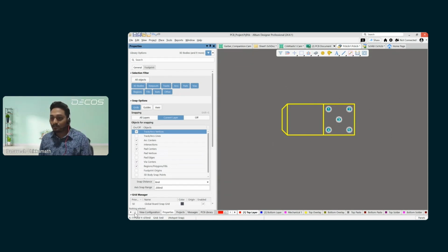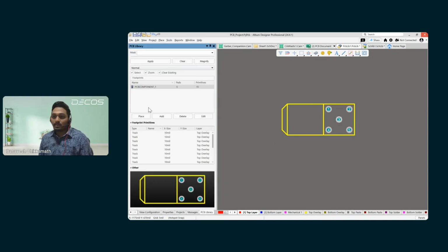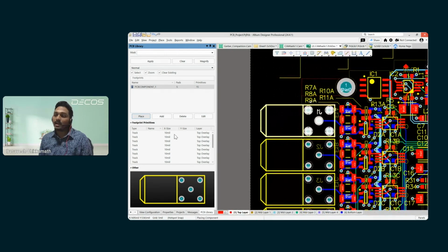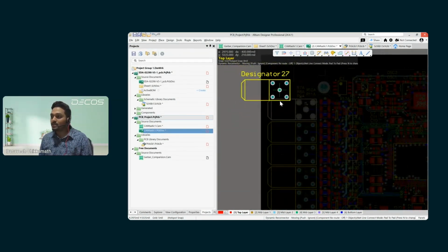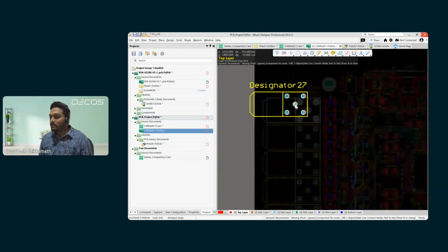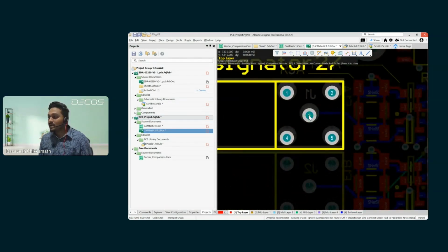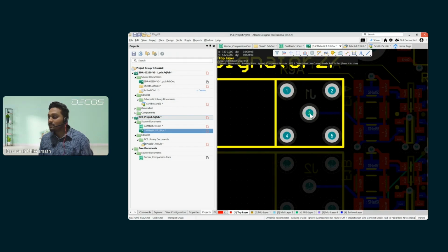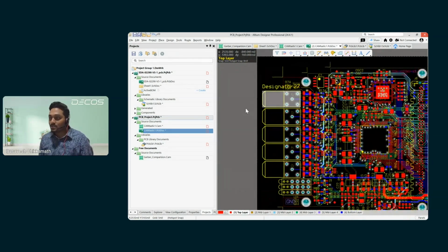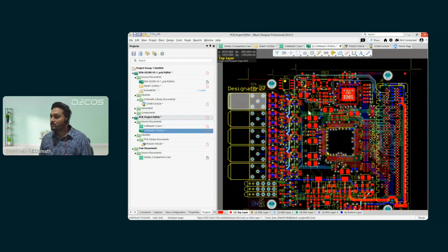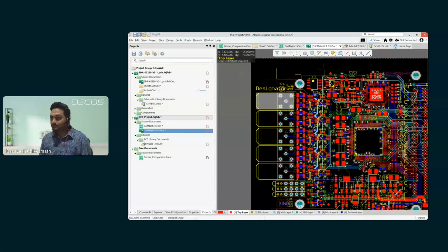Once you have done that, here on this PCB library window, you can notice we can place this particular footprint in the PCB simply by clicking on place, and it will navigate to the PCB file and bring that newly created footprint to the PCB. Place it exactly on top of the existing pad or the C lines. Follow this process for all the components which are present in the PCB.